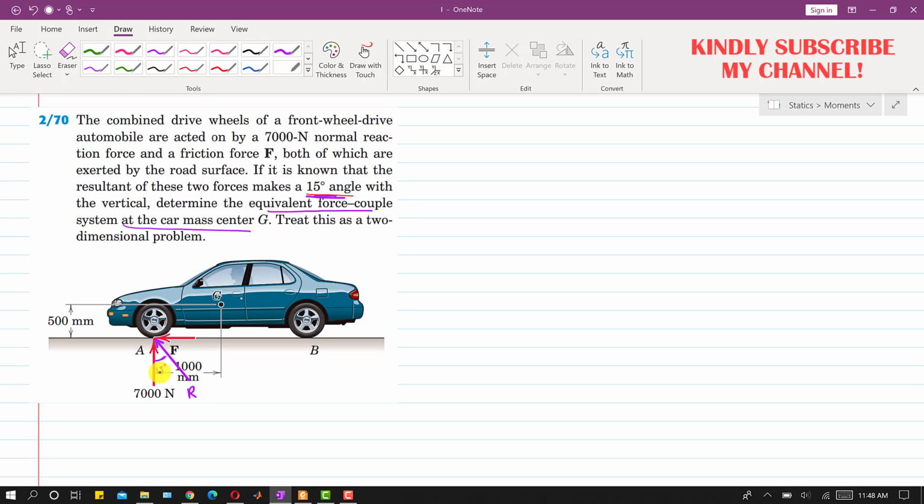Now as we can see, if this is 15 degrees, then this 7000 Newton is the cos component of this resultant, right? So I can say that R cos 15 degrees equals 7000 Newton. This will give me the magnitude of the resultant of these two forces. So R will be equal to 7000 divided by cos 15 degrees. So R equals 7246 Newton, right? This is the magnitude of the resultant of these two forces.